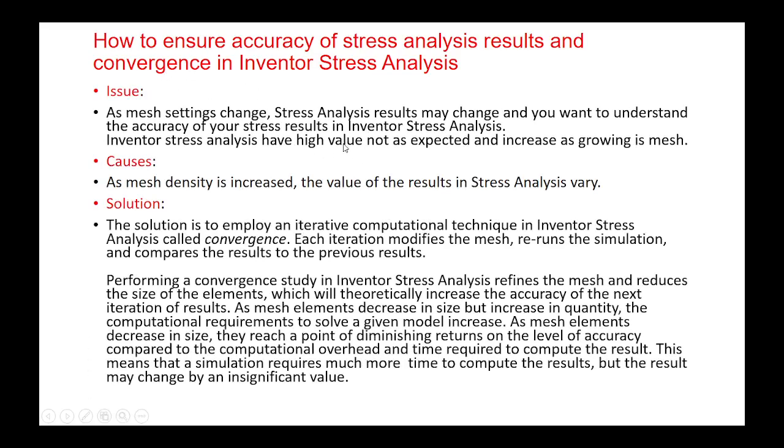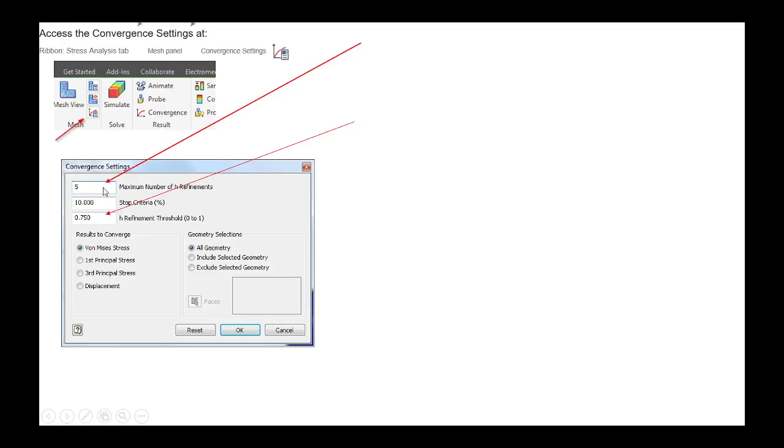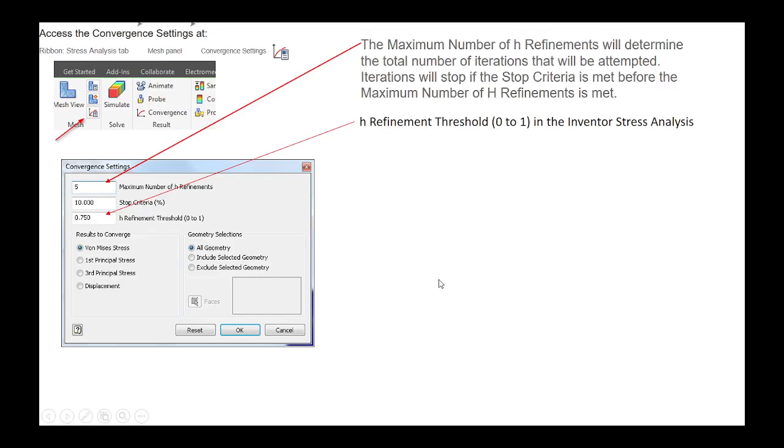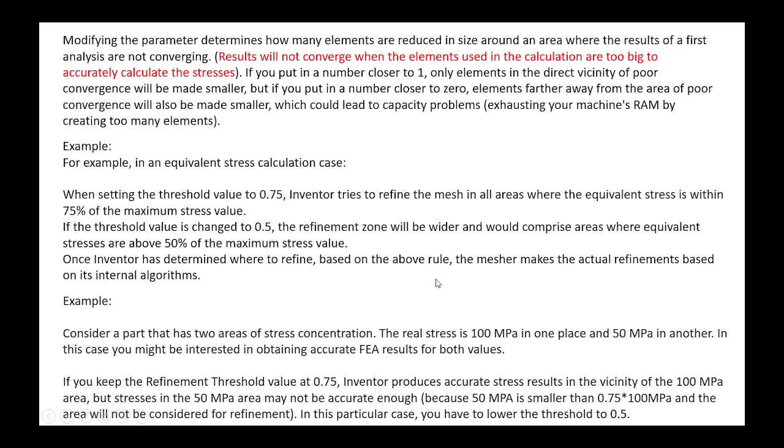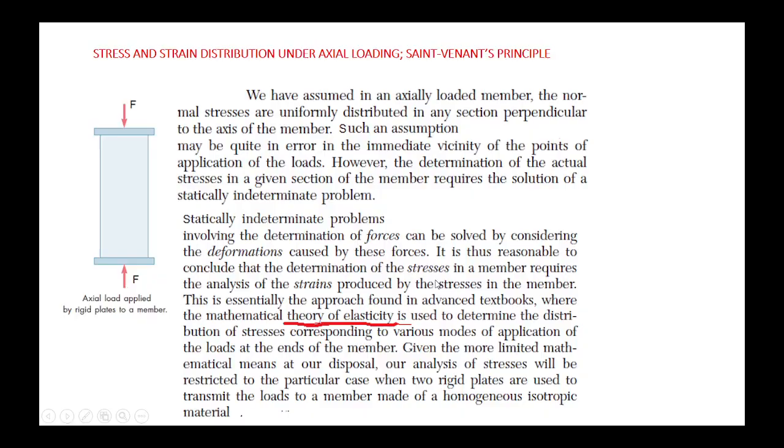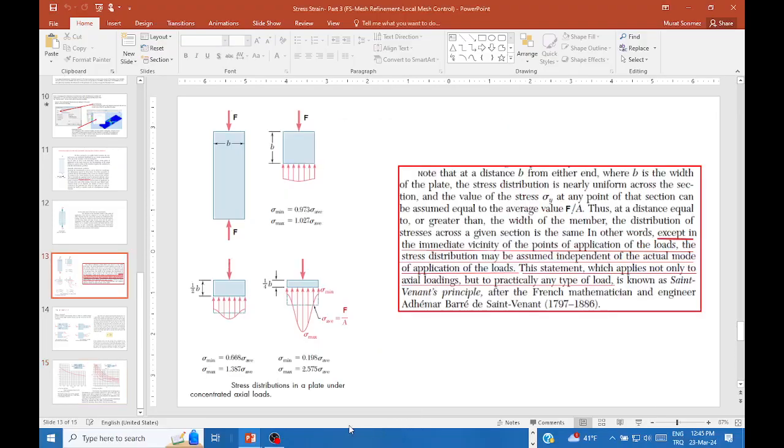Okay, well, enable the software to repeat the solution n times, but for each repetition say that use a smaller mesh size where the stress is maximum, and also in this example, 75% of the maximum stress or greater. Only such parts use a finer mesh. Okay, and then to be able to study both of the techniques, the example I selected is this one.